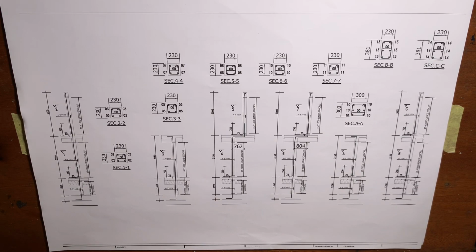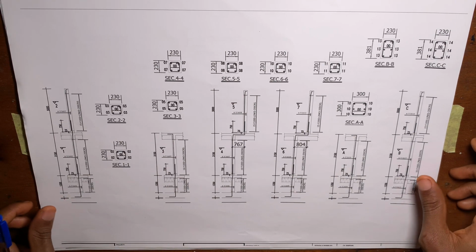Now, if you look at this drawing, right, this drawing shows the placement for the starter columns from the substructure down to the first floor. You know, this is the ground, this is the foundation work, this is the ground floor, this is the first floor. So now our concentration should be on the foundation, because we want to measure the substructure of this drawing. So now if you look at this thick L shape here, right, you see that what we have here is the same thing we have in the section of our column base.